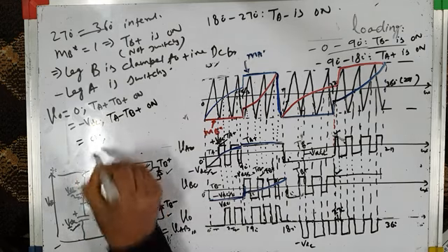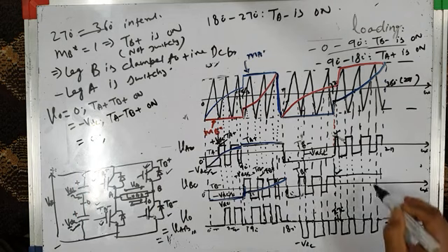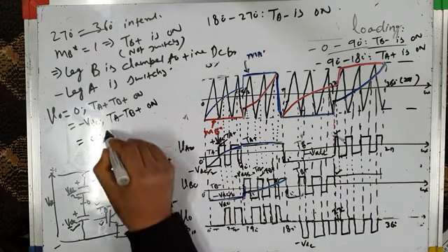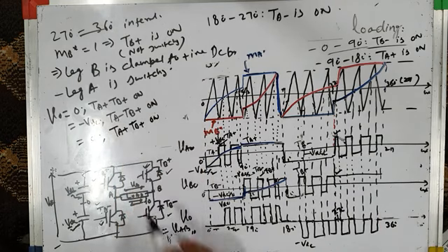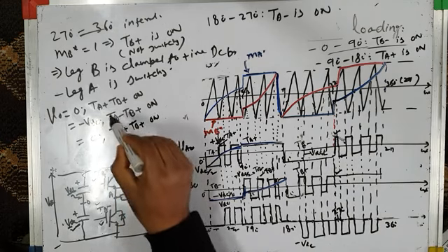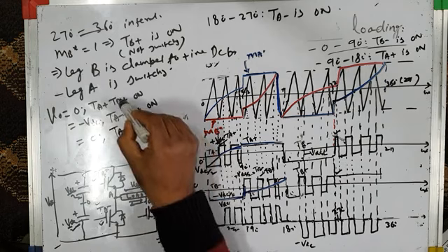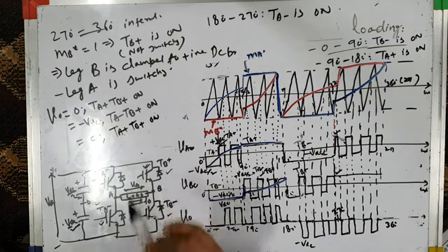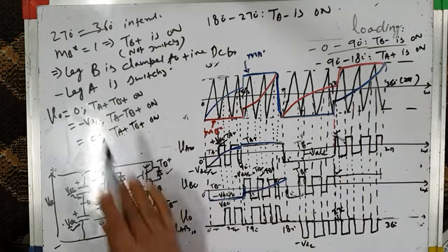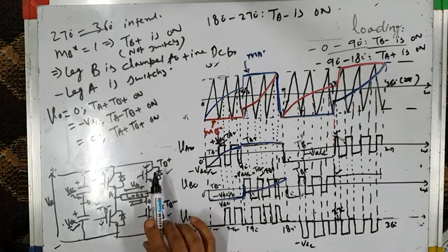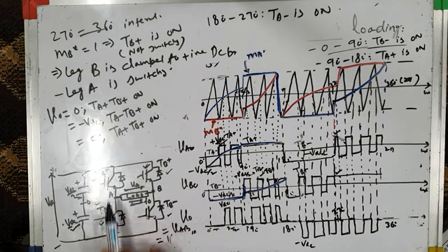And it is again equal to 0. It's again equal to 0 when the top switches of both the legs are on, TA plus and TB plus. Now you can see TB plus is on here, here, here. So TB plus is not switching. That's already known to us. Phase leg B is already clamped to the positive DC bus. Leg B is not switching, but leg A is switching.